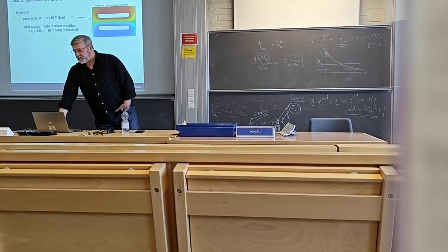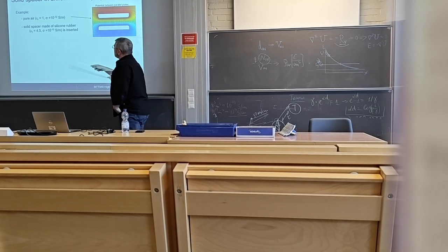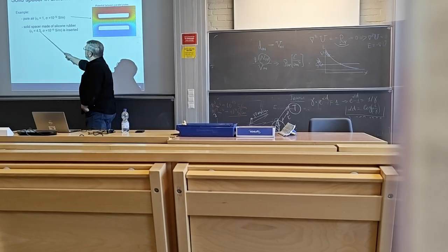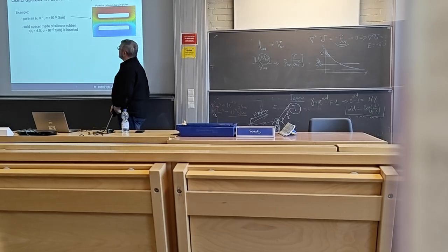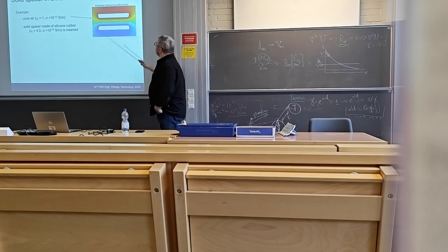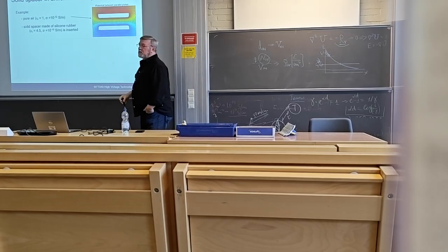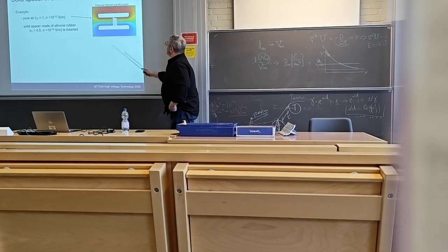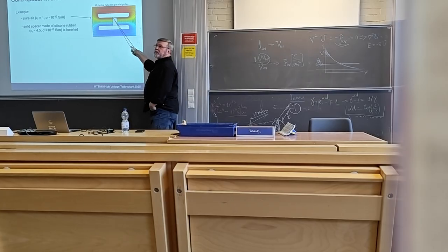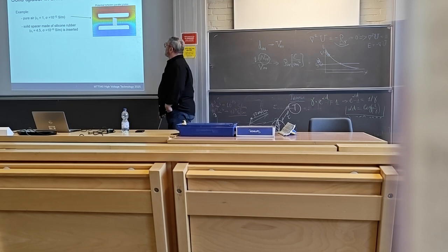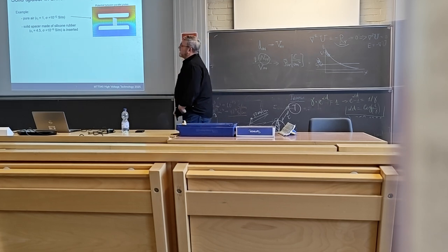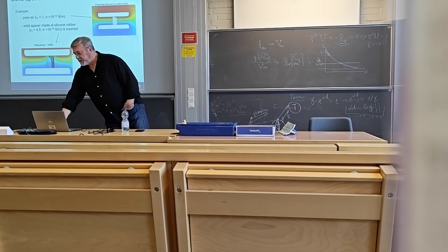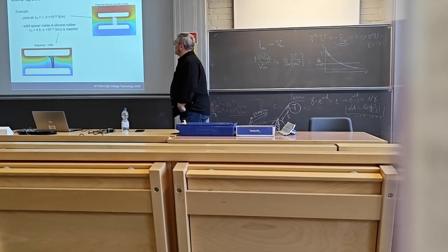If you have a solid spacer, just a piece of silicone rubber, which has high permittivity and lower conductivity, you just insert it somewhere here in the middle, and it has some special shape like this. So touching the electrode in one point, and here is the full contact. So what will happen? If you calculate the field, you will have it like that.